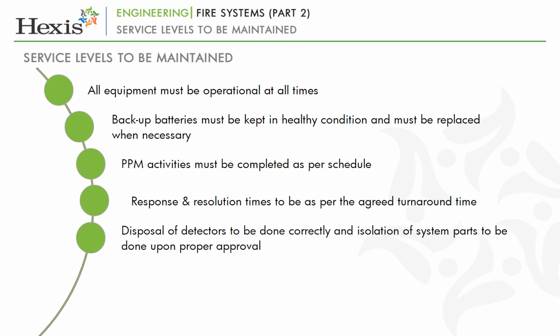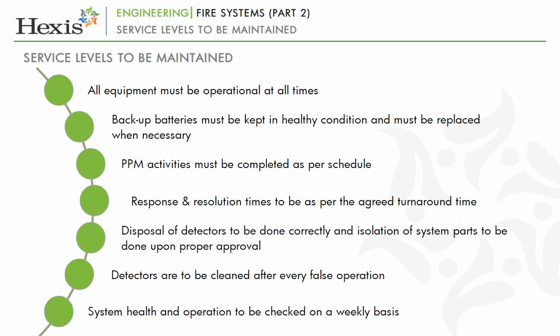Any isolation of parts or components of the system must be done only on approval and system restored after completion of activities. Detectors are to be cleaned after every false operation. System health and operation to be checked on a weekly basis.